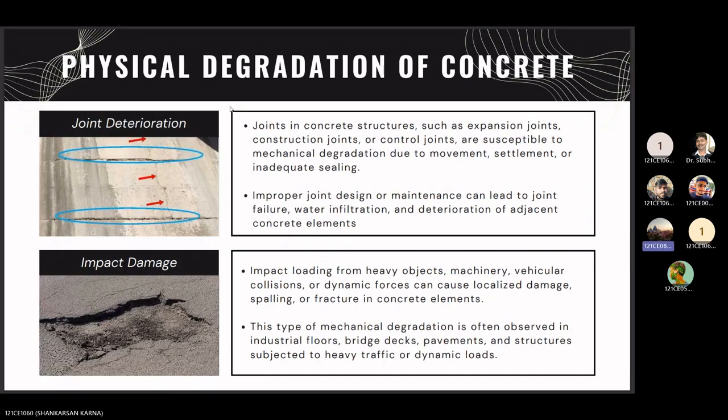Joint deformation. Joints in concrete structures such as expansion joints and construction joints are susceptible to mechanical degradation due to movement, settlement, or inadequate sealing. Improper joint design or maintenance can lead to joint failure, water infiltration, and deterioration of adjacent concrete elements.